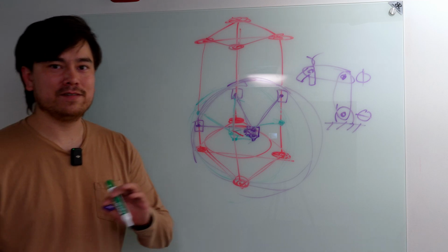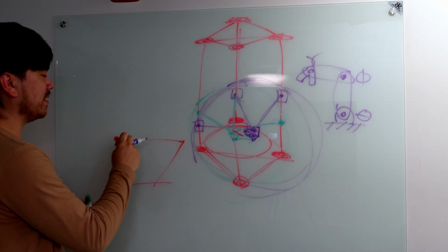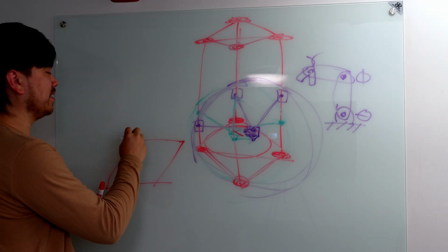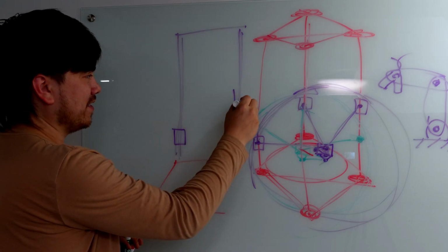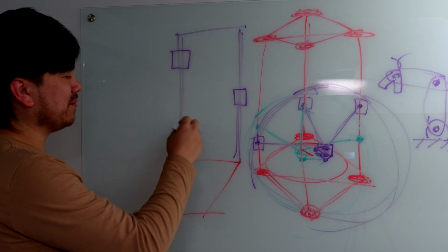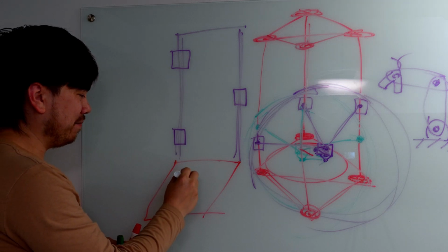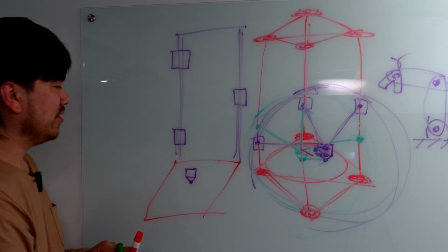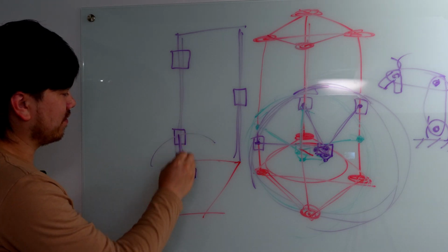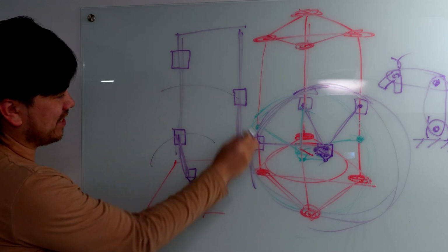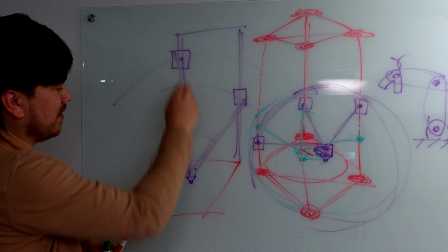All right, I'm not gonna get too much further into the math and the geometry of these mechanisms. Although I do want to tell you one last thing: there's a way to make a delta mechanism that just uses 2 linear rails, 3 blocks, and some system of different length rods to make a 3D printer like this. You would just have, let's say all 3 of these rods were different lengths. You'd have one sphere intersection for your first rod, another sphere intersection for your second rod, and then another spherical intersection for your last rod there.